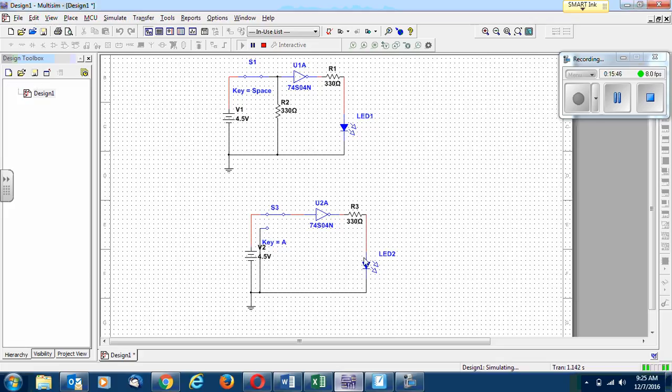and the LED is off. Now, one thing that is not helping us build a tripwire in this particular case, this particular switch looks like a broken wire. And this one really doesn't. So this is a true circuit for the tripwire, and this one is more of a simulation circuit, because you have to use the pull-down resistor over here to get that working. But it is useful to know about the existence of this switch, and we're going to use that switch a lot in this class.